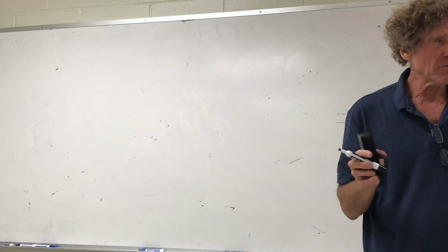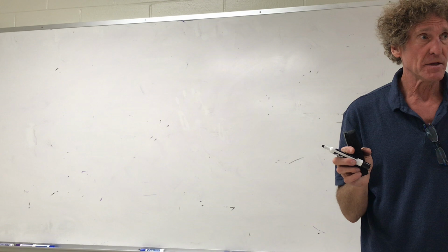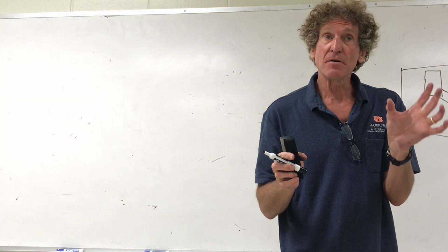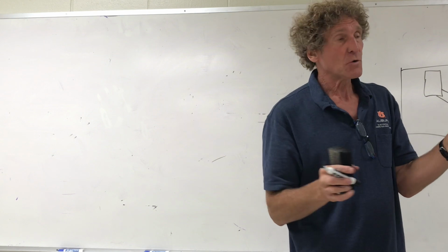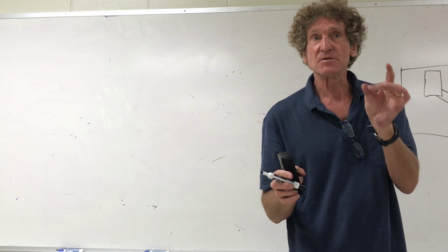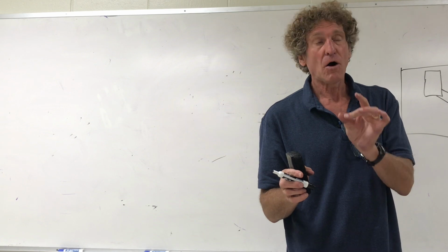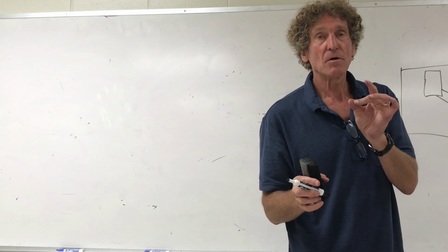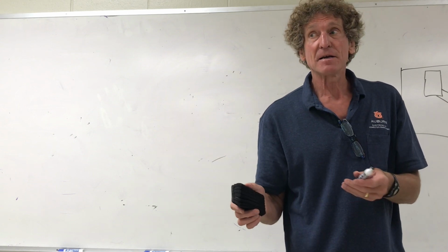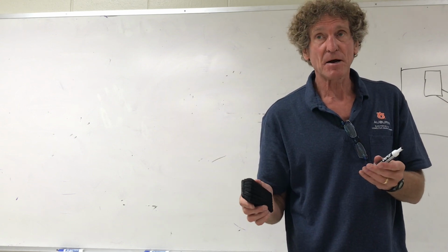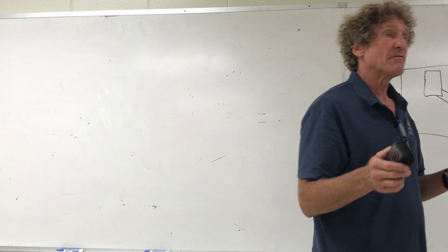When you have a very small amount of board to work with, that real estate is very valuable. You would like to mount things there. You don't want just a line going out. So what they'll do is they'll mount devices, typically capacitors, on the board that will impedance match what's coming in to what's going out. So instead of having shunts in series and parallel, we're going to have real values.